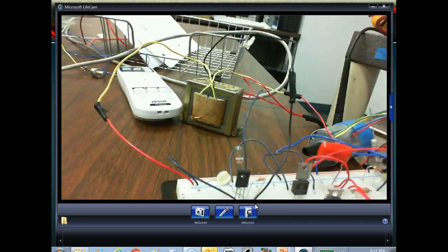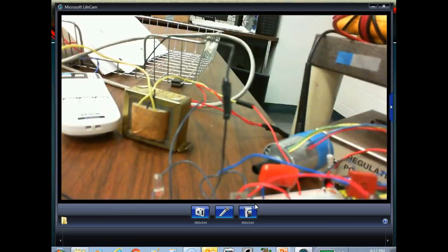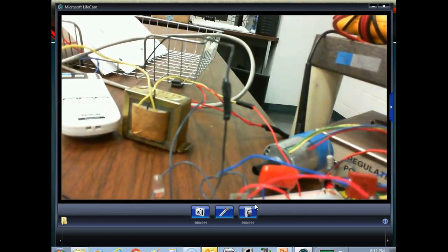Now these guys will get warm because they got two junctions in there. So you know that's going to be about 1.4 volts drop across there. And if you put a lot of current, like I said, 100 amps through a triac, that's still 140 watts, right? You understand that? So these guys will get hot. They'll be heat sinking. But if we tried to do it with a rheostat, my rheostat would be as big as my house, right? You understand? Because when you drop 15 volts at 100 amps, that's a lot of watts, right?